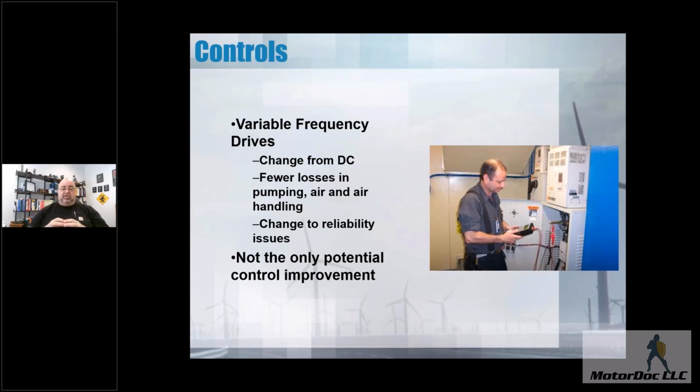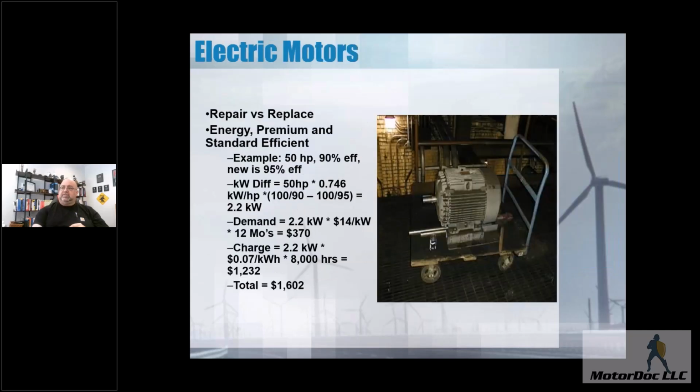We just did a survey of a plant in which we saw, let's see, the phases were about 300 amps each, and there was over 100 amps sitting on the ground. So that was a significant issue.